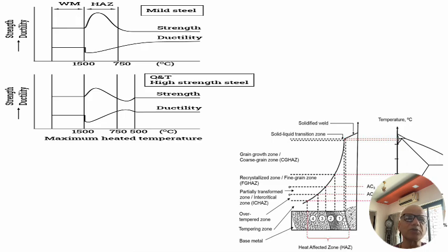So in summary, for this particular topic, defects are internal, within the weld, and defects are external to the weld. Visual defects are there, and NDT detected defects are there which are hidden inside the weld. There are defects coming from poor setup, and defects coming from poor fixturing, or not using a neutral axis or balancing the weld, or not using a proper technique like the step back technique.